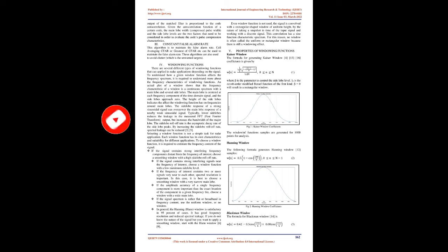The received signal is fed to the matched filter, whose frequency response is the complex conjugate H*(f) of the coding filter. The output of the matched filter section is the compressed pulse, which is given by the inverse Fourier transform of the product of the signal spectrum H(f) and the matched filter response H*(f).